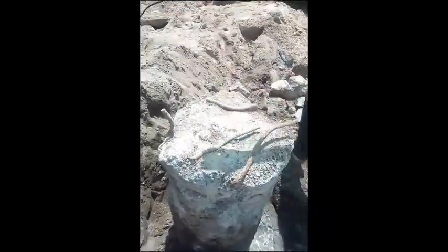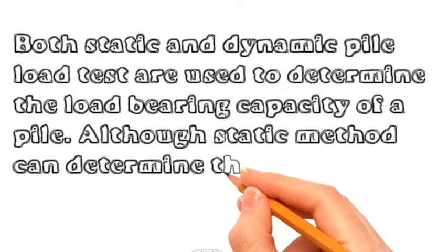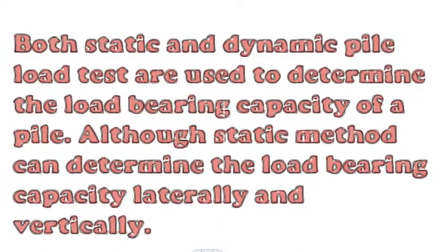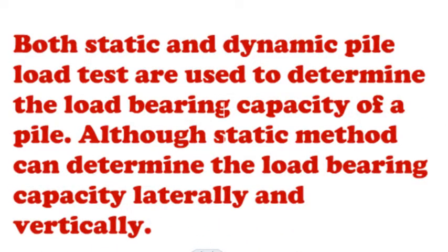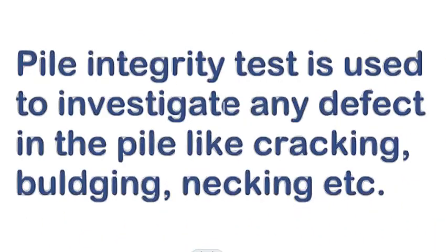In summary, the static pile load test and the dynamic pile load test are used to determine the load bearing capacity of the pile, but the pile integrity test is used to determine the integrity of the pile. You know what integrity means.